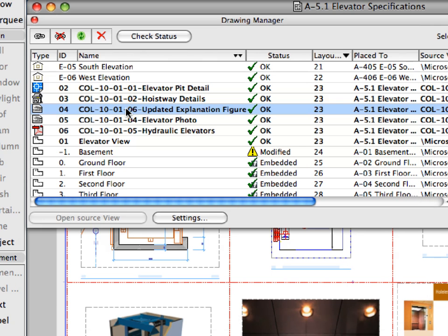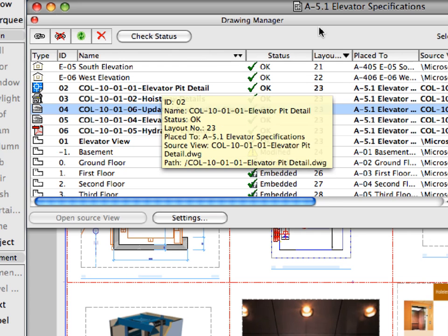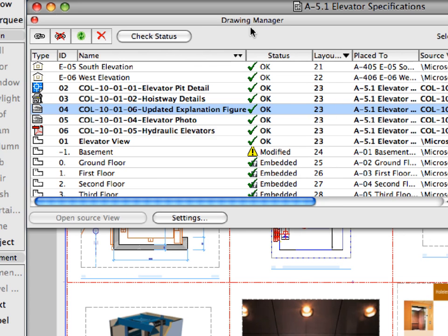Notice that the file name changes in the list. The source file of this drawing has now been changed. Relinking an existing project hotlink to a new content source can be useful if you wish to keep all the previously defined drawing settings and drawing positions in the project, such as drawing title, scale, and so on, but you wish to change drawing content.